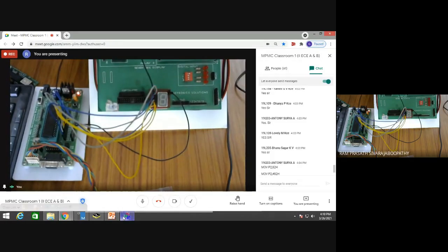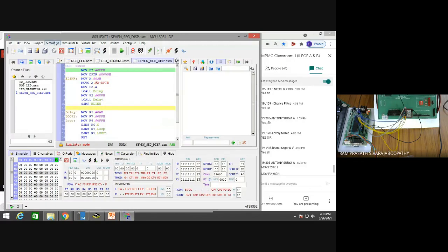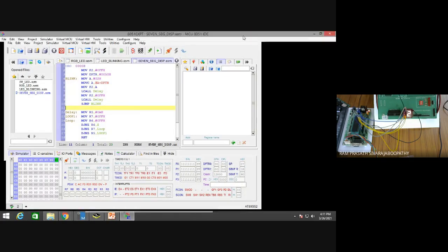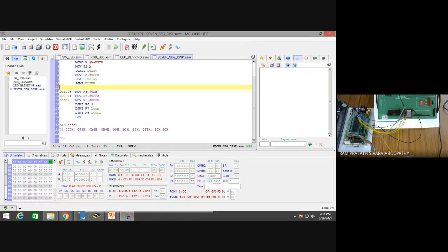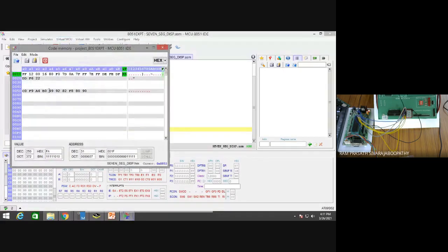So kindly take a screenshot of this. Later point of time we can go with this. We can discuss programs like this later. Fine. So kindly take a screenshot of this program. Here we have used an assembler directive. Its meaning is define bytes. DB means define bytes. The bytes that come after this get stored in memory at 0050. You can see, stored here is the 7-segment code for numbers 0 to 9. That's it. Okay.